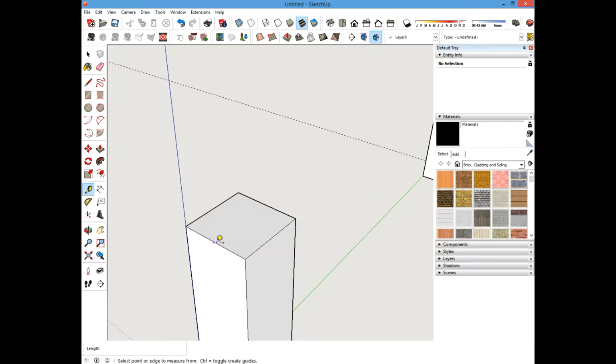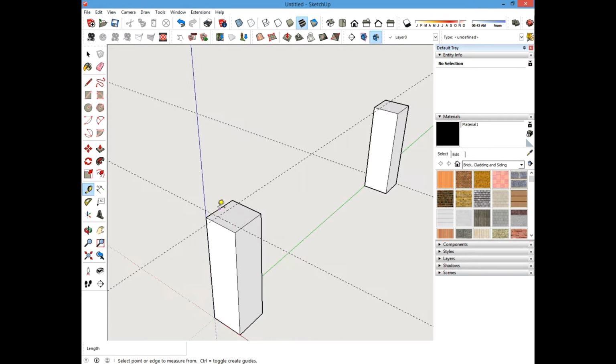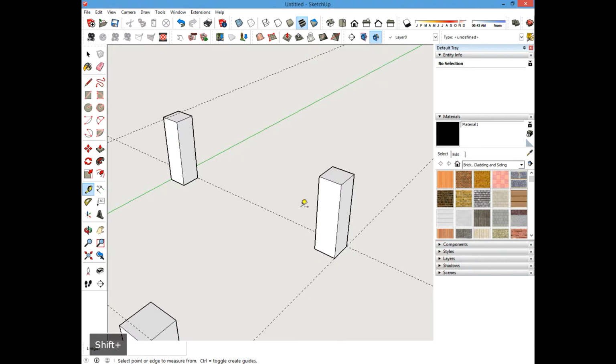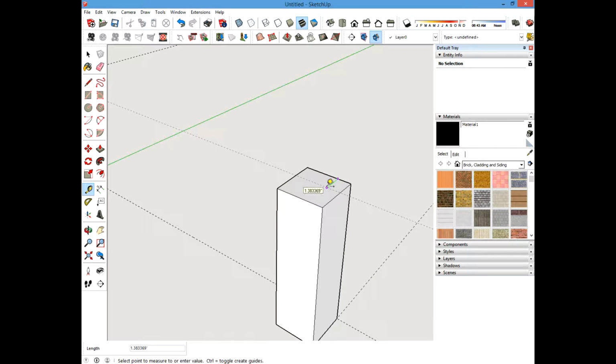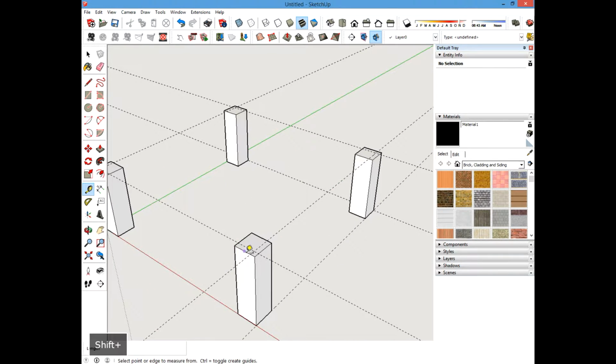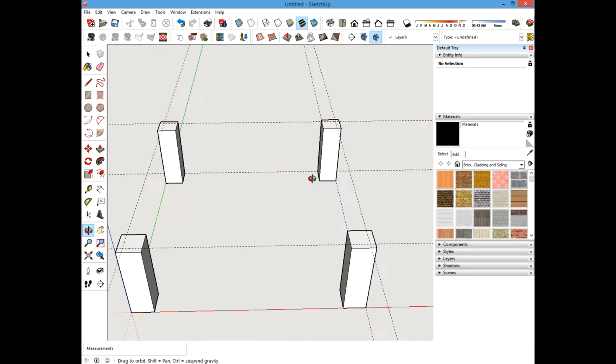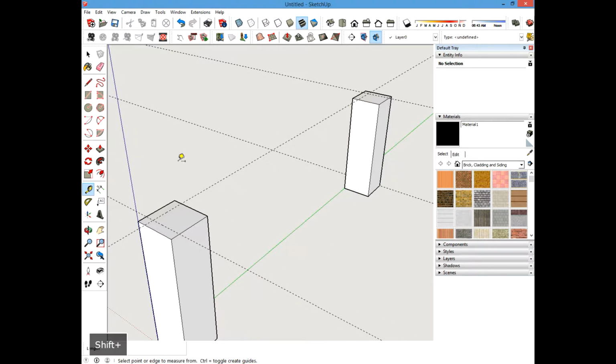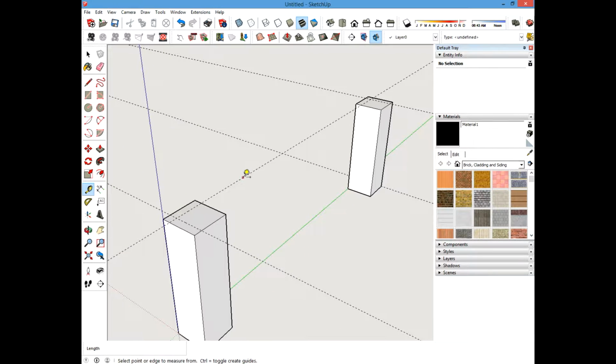So what I'm actually going to do is offset lines using our table legs as reference, and I'm going to offset it 0.75 inches on each side. You'll see why I do that in a second here, but basically I'm leaving some room so that we can come back in and put the other boards that will fill up that gap. Okay, so now for my first board,